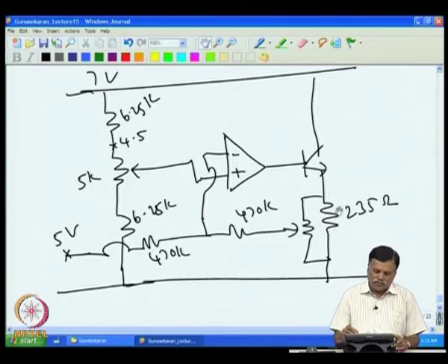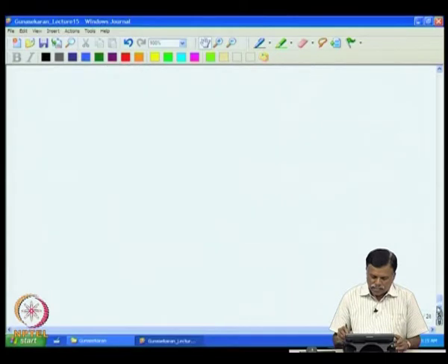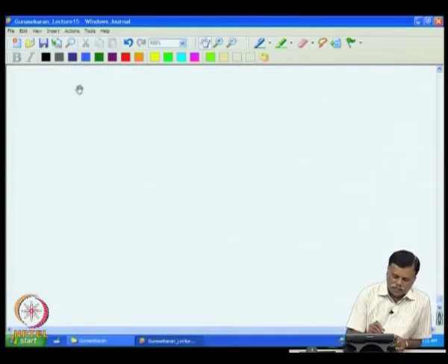So, essentially first find out what is the offset voltage drift here, then the same drift is expected here, then the voltage change that is required here, then find the expected voltage change here. Once you know the expected change in voltage here, then resistance is known, and the current change can be computed. So, we go step by step. Now we are calculating the error due to offset voltage drift.